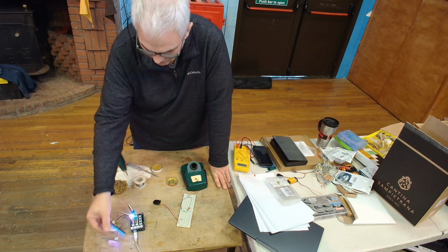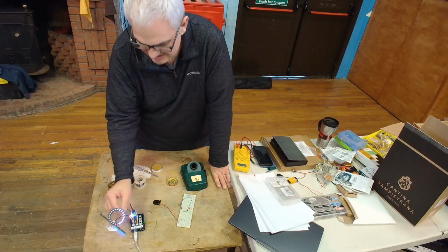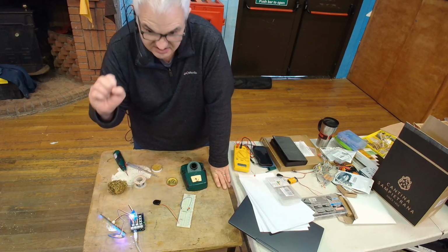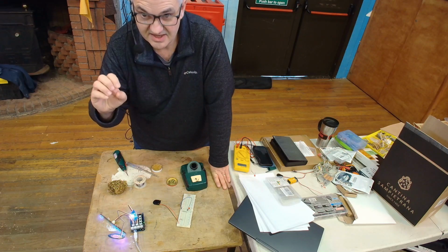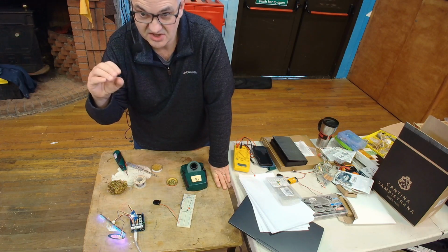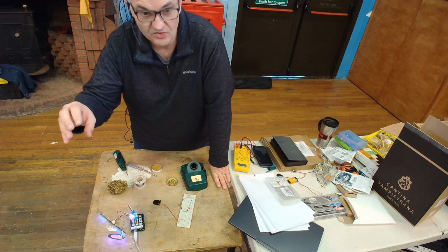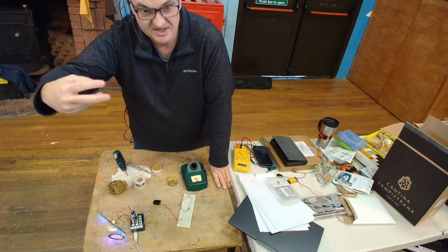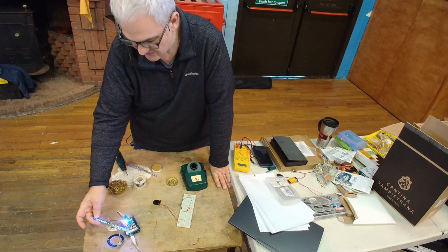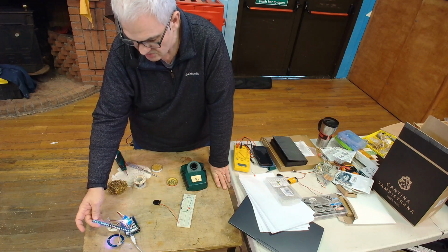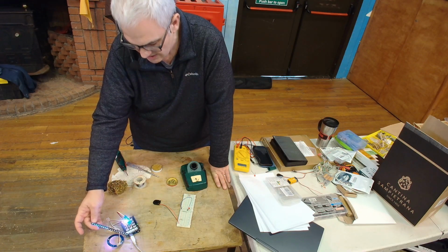So what these actually do to change the intensity is switch on and off really quickly. It's continually turning the light on and off, and the more it's on, the brighter it appears to you to be. That's how they're using different combinations between the three LEDs to get the different colours.